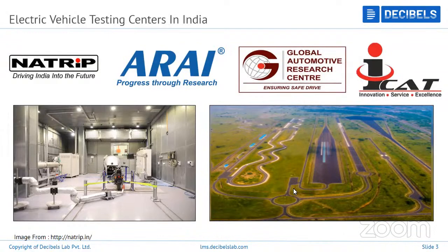And again, when you look at the test tracks, you can see some test tracks for the slalom. You can see the test tracks for the braking distance, stopping distance, gradability. There are tracks with certain predefined grades, 7 degree, 13 degree, and what the acceleration was on the gravel road, tar road, mud road, sand, and what the braking was on all different kinds of roads. So this picture completely depicts that these are all predefined areas. It's completely different in a day-to-day scenario, right?